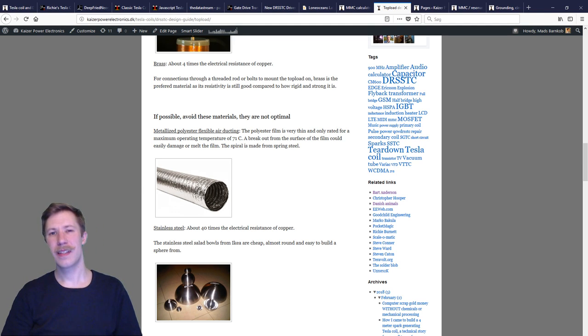What is really the deciding factor here is actually your MMC capacitance, because this is the amount of energy that you dump into each spark. So low impedance coils will produce thicker and heavier sparks than higher impedance coils. You can simply not fix it by adding longer on time, because you do not control the spark channel over that long amount of time.